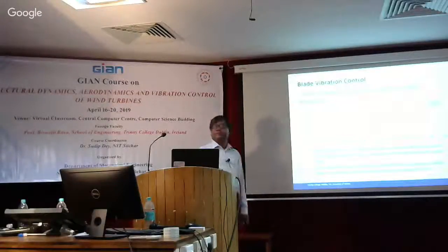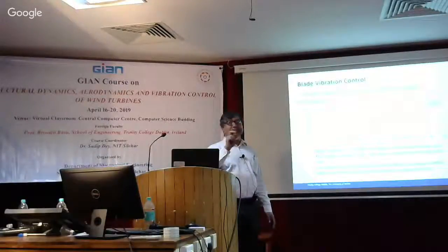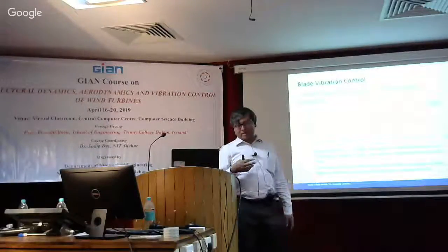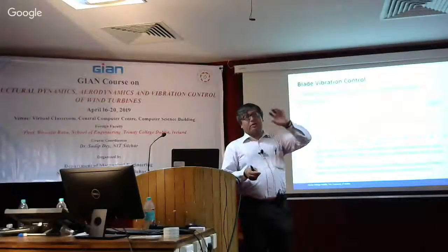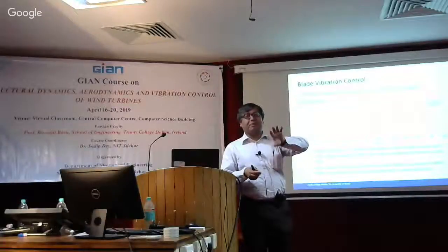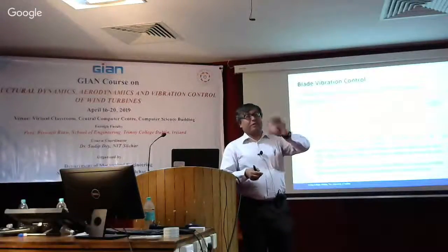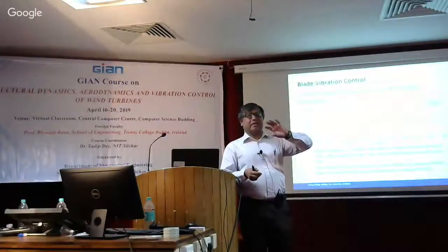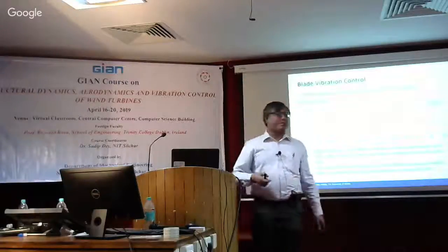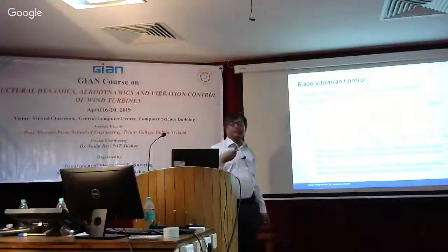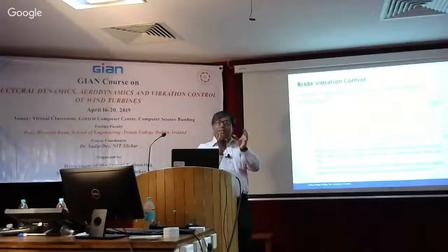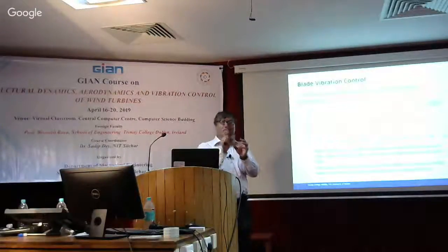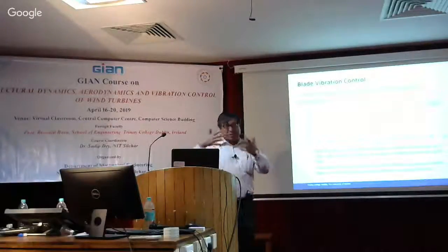We can also go for an undamped tuned mass damper. No, you can't, because that will destabilize the system. So what happens is, if you take a simple 2-degree of freedom system and a rotating system, rotordynamics, and tune the mass damper to the natural frequency without any damping, then you look at the eigenvalue problem, what you'll find is one of the frequencies basically makes that whole thing unstable. Essentially, there's a rigid body motion. Because of the tuning, what happens? Tuning modifies the frequency of the system, or essentially the stiffness of the system. And if you go for perfect tuning, then the stiffness of the tuned mass damper effectively becomes 0.